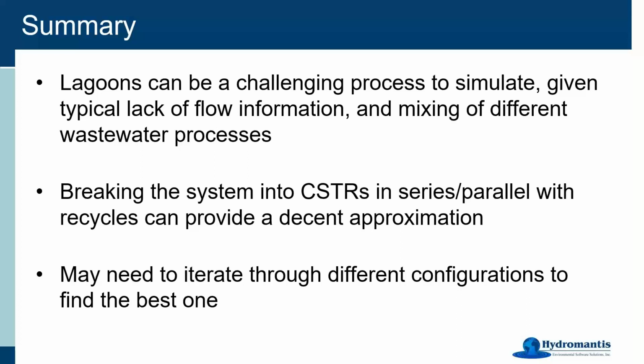So just in summary, talking about all of those methodologies that we presented earlier, and as you saw them applied in our case studies, lagoons certainly can be a challenging process to simulate, given that lack of information. But the approach is generally to break the system into CSTRs. Some of them will be aerated and some not, and whatever is appropriate for your particular system. And that little challenge of trying to find out which way they go together, where potential recycles happen, and so on, can give you a decent approximation.